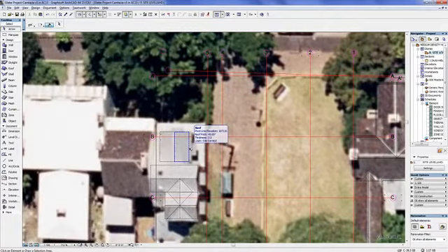So I've determined that a rough RL to the ridge here, so these ridges, is 109,560. Okay, this is just an educated judgment based on the photos. Then this one here is going to be, say, 109,180, which is, let's see, 560, 109,180, about 380 mils lower. So this is going to be 380 mils lower. So to do that, it is most accurately done in section, okay?